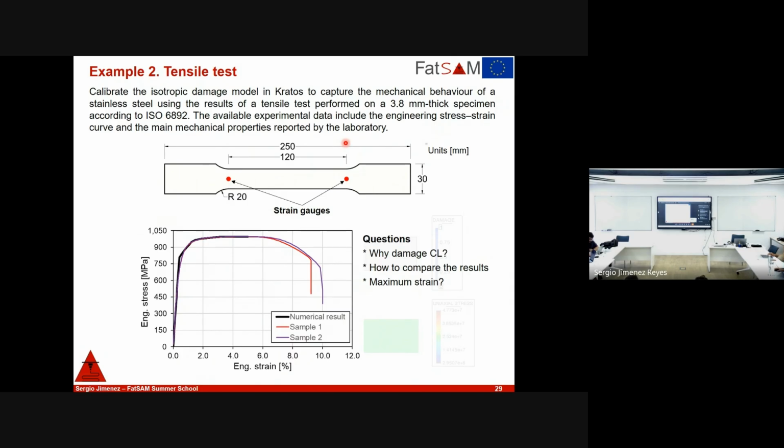What I want is to ensure that everything is under elastic mode, because I just want to run the simulation, make sure that works, I don't want to do anything else. Then the definition of the load I can read directly from the JSON. So let's take this here and let's assign it to the correct one. So this is not set. Then let's apply it to this only.